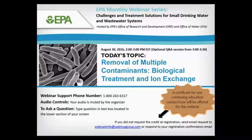Okay, great. Here's another question for you, Dr. Boyer. How long does it take to regenerate the combination of resin? Is it different than regenerating each one separately? No, that's a great question. We looked at that in some of the earlier work, and we looked at separate and combined regeneration, and there's no change in the combined versus separate with respect to time. The cation exchange is a rapid process in terms of the regeneration. The anion exchange process can take a little longer because of the larger DOC molecules. So really it's thinking about the contaminants and the resin properties for the time to regeneration, and whether it's combined or single is really secondary to the contaminants and the resin properties.